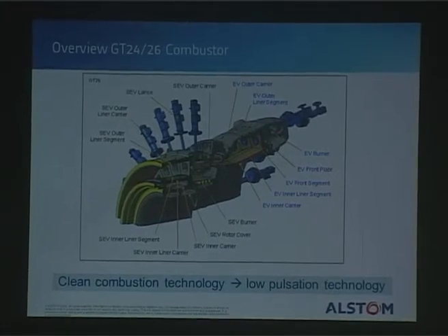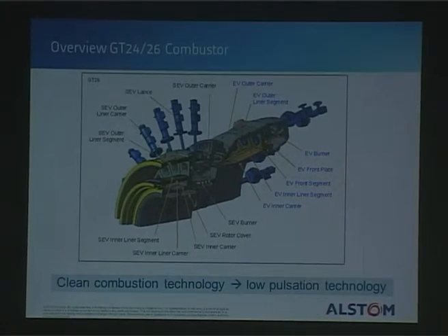And also in terms of operability, if pulsations are above a certain threshold, the engine would simply trip, and you want to avoid that. So the lower your pulsations are, the more flexible you are, and the better you can operate the engine.